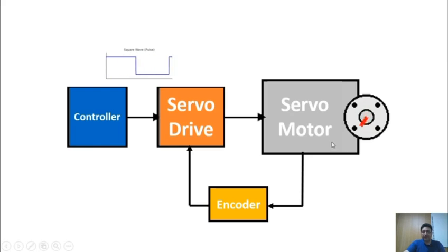And as we clearly explained in the previous lesson, servo motors are equipped with an encoder which acts as a feedback device. This encoder provides important information about the position and movement of the motor shaft. We can connect the motor's encoder cable directly to the drive, and by doing so, we are able to receive continuous feedback from the motor's movement. This valuable feedback allows us to achieve much more precise and accurate movements in our servo motor, ensuring that the motor operates exactly as intended.